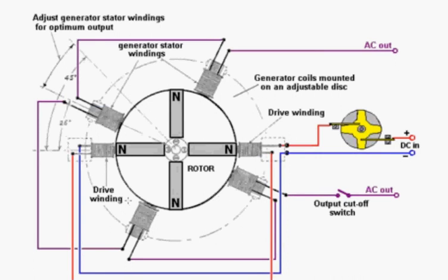Now, everybody will tell you, oh, you're going to lose power through eddy currents going sideways in those cores. Well, the answer is yes, you do, but you gain more than that because the output from the coils is bigger than the eddy currents by a long way, due to the stronger pull of the rotor magnets. Okay, so what happens is, when you start off, a rotor magnet gets drawn across to one of the two drive coils, the core of one of those two coils, or to one of the four output coil cores.